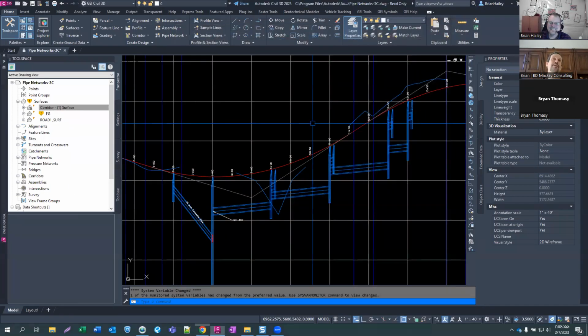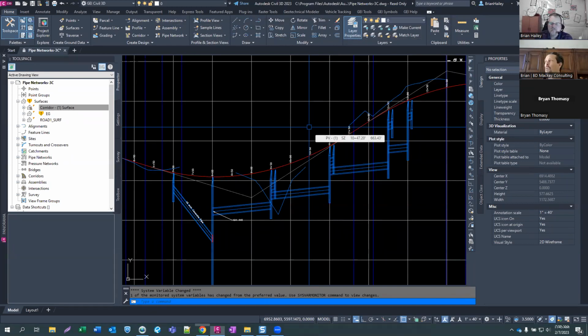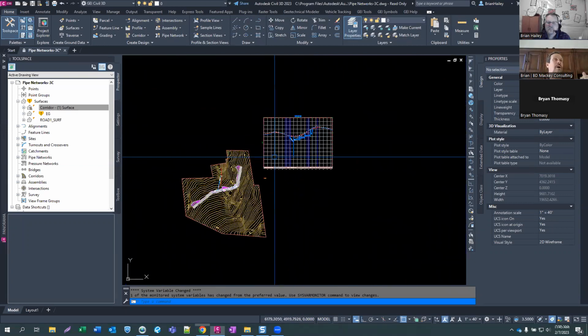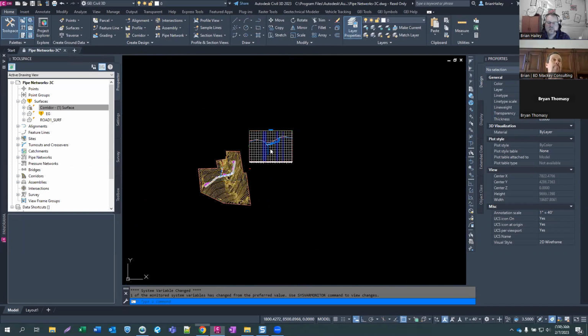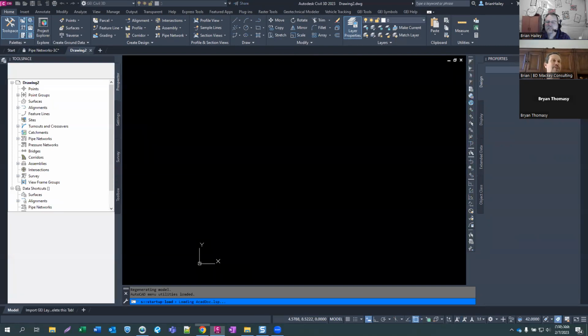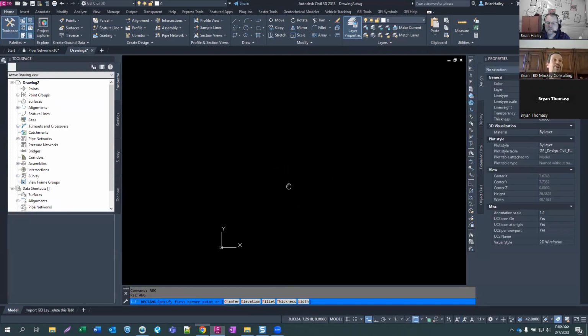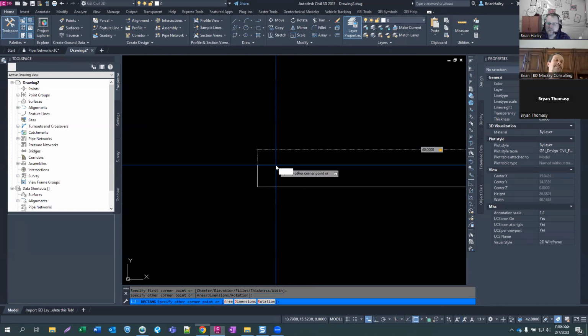I opened up a file in Civil 3D and it actually had Live Map turned on where it was constantly downloading. What exactly is that? I just said don't turn it on, and then realized, by the way, that it completely screws up Revit, because it takes a little rectangle and draws it in at the 0,0 point of your Civil 3D file, but you can't see it inside of Civil 3D or AutoCAD. Yeah, Live Map is basically the Bing imagery. The only way I found it was in Revit. I could query the rectangle and it said, oh, it's the map image. If I go back to AutoCAD, there's no map image here. So I just started typing in map and, oh, look at this, there's an image thing in here.